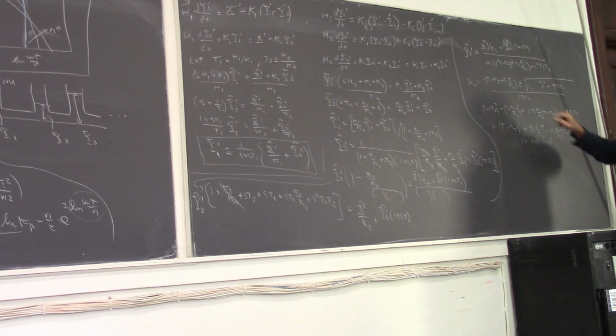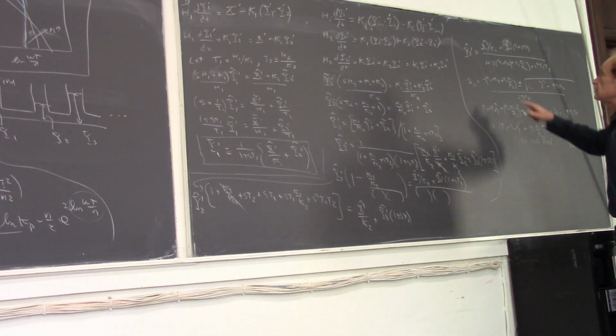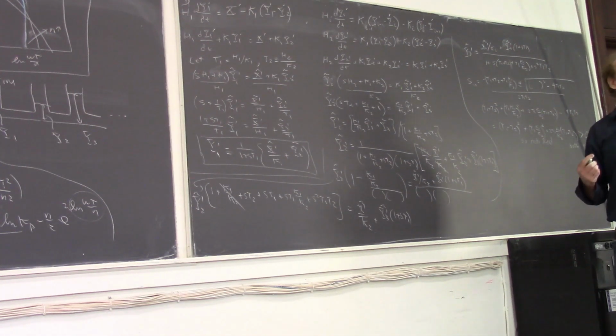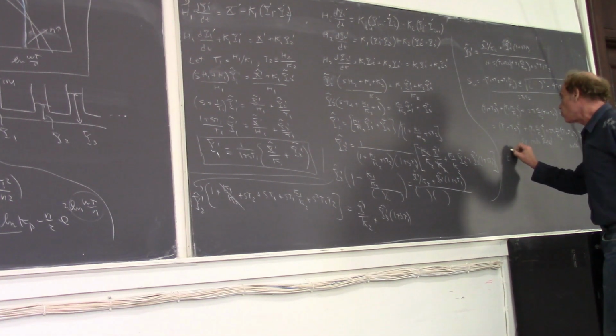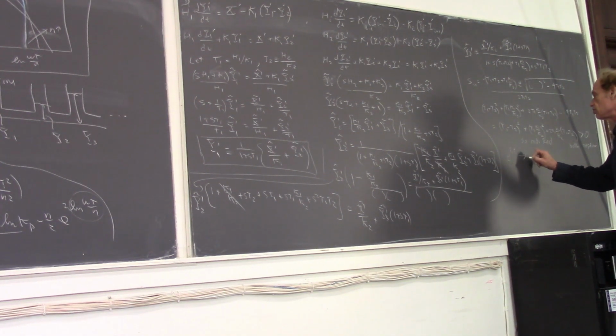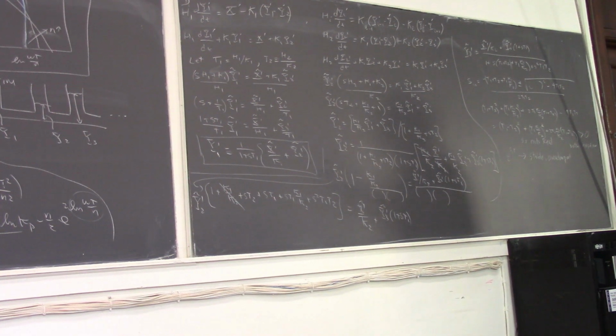And this one is clearly negative. They're both negative. So as a result, both roots of the denominator are real and negative. If they're real and negative, that means when I get either the S1 or S2, these are real and negative, these are going to be stable and overdamped. Meaning, they're going to decay exponentially.